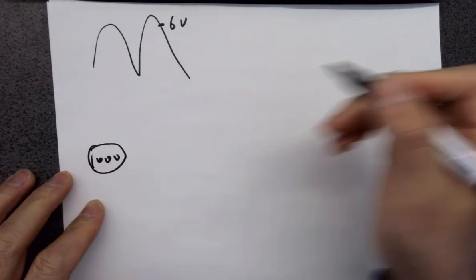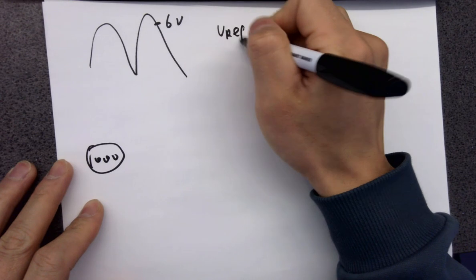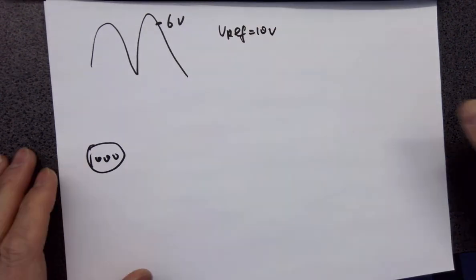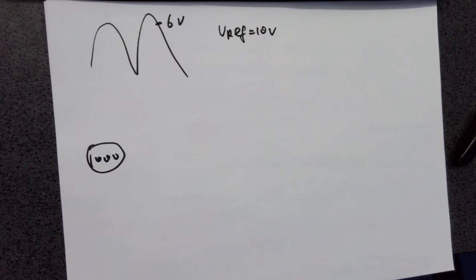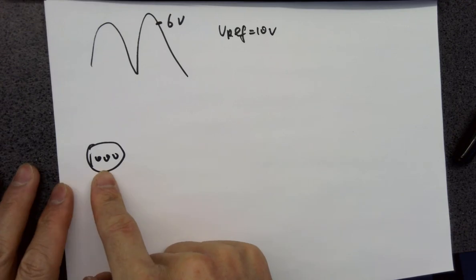Always 50% of the range. So you're just throwing that 50% of the full range into the system to start with, so you can compare with the analog input. It doesn't matter which is larger or smaller. The SAR logic is going to handle that. But you just need to have a number to start with, okay?